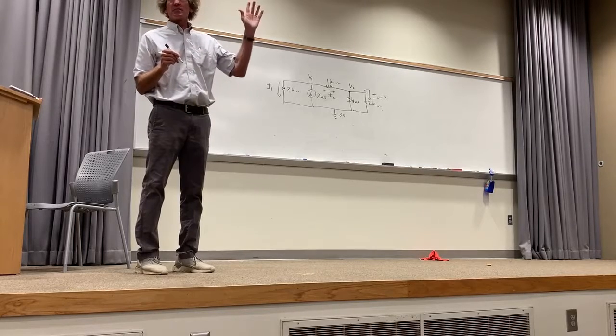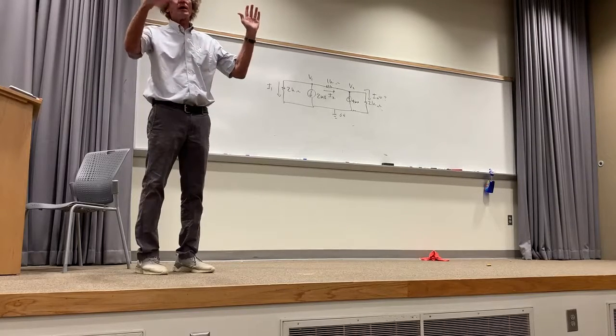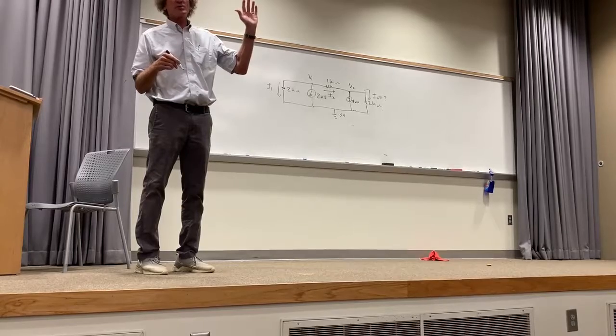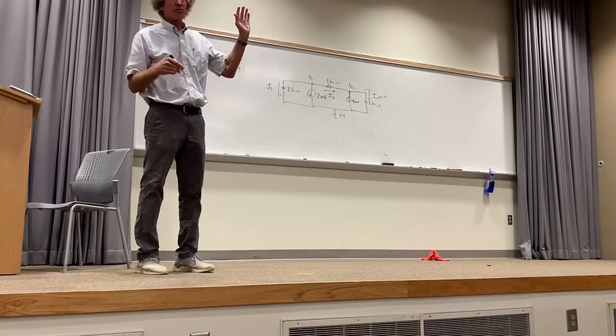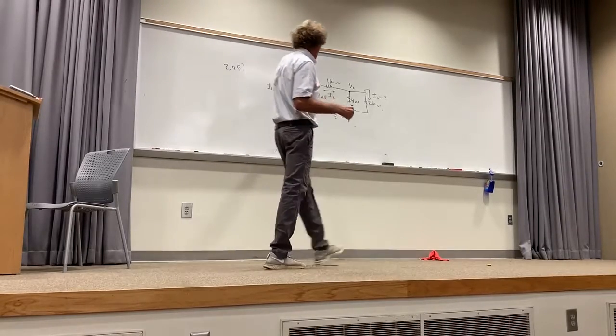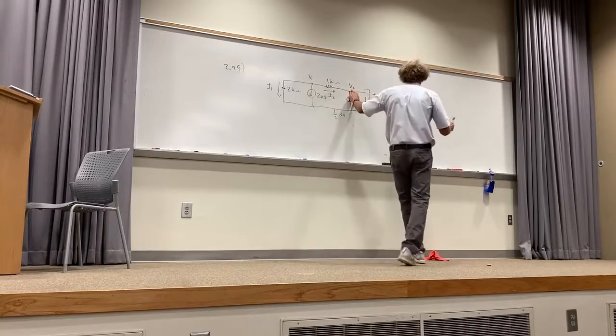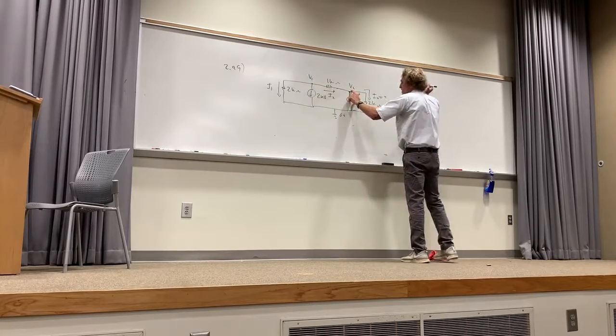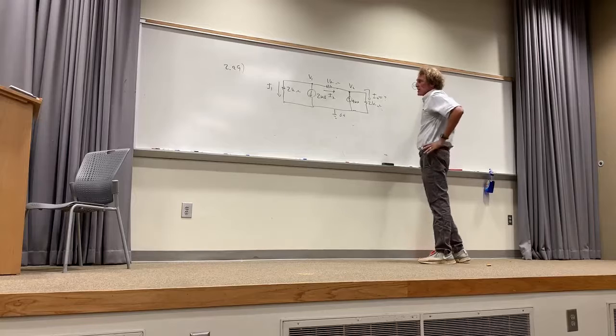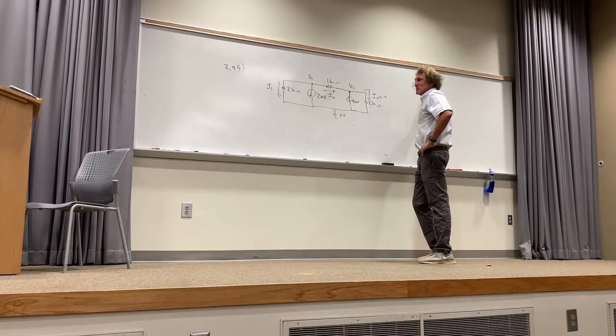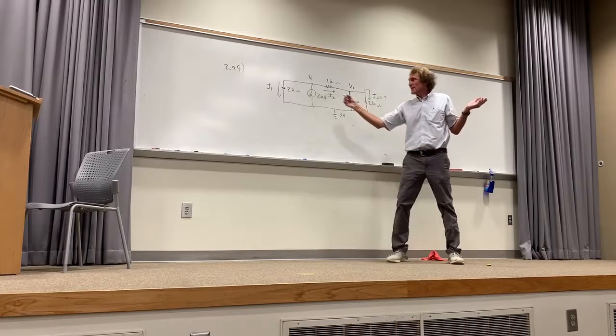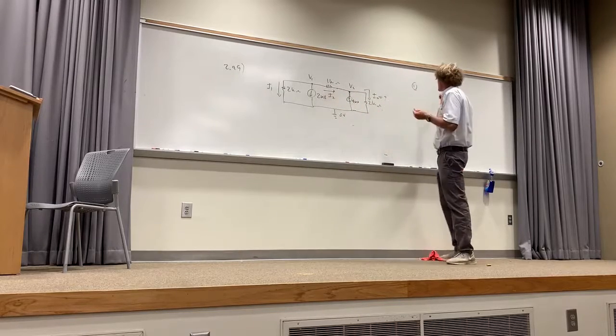How many see this? Now you simply write the equations for the currents going into those nodes is 0 on these nodes. You can call that node 1 and this node 2. For node 1, what are the currents going into it? Take a look. How much is going in? Is anything going in? None. So it's 0. This makes it nice.